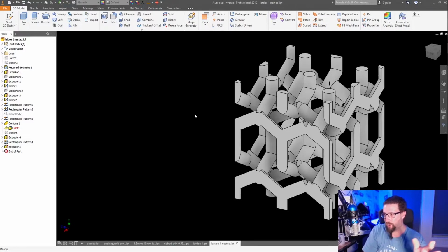So these lattice structures work, but in order to get them down to that 95% density reduction, you need to scale the lattice structure up. And by that point, again, the points at which the lattice touches the skin of the wing are further apart. So you're getting less force transfer than you really need, and you end up with a weak part anyway for no gain. So I think it's the final nail in the coffin for gyroids and lattice structures. Yes, they're neat and all that, but computationally, the amount of effort you have to do to make these structures, to get them to work, to boolean them, they just look cool. They're not actually practical in many cases for what we're doing.